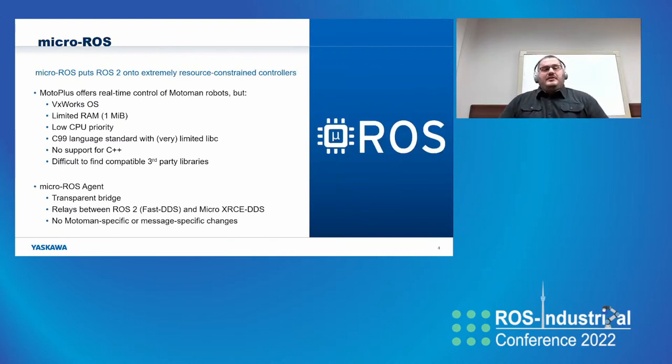As I mentioned before, we are running on the MotoROS platform, which was designed primarily for microcontrollers with extremely limited resources. On the Motoman, we're building this using the MotoPlus SDK. MotoPlus is not necessarily an embedded platform such as a microcontroller, but it does have limited resources, limited memory, limited CPU, different C standards, and MotoROS was helpful because it let us run on this constrained environment.